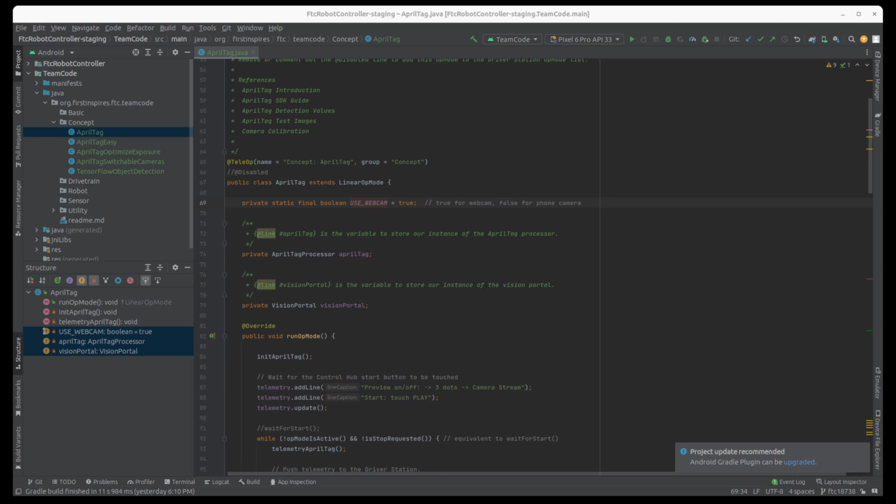If all the tags in the camera image are detected, then that combination of exposure and gain values is deemed practical. There are other camera settings beyond the two in this OpMode that may improve the detection of April tags, particularly when motion is involved. These parameters will be explored in a future tutorial.